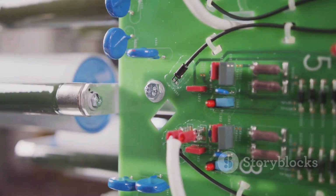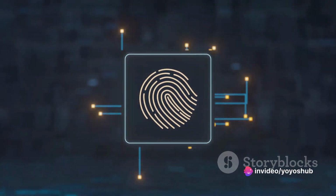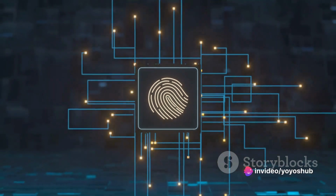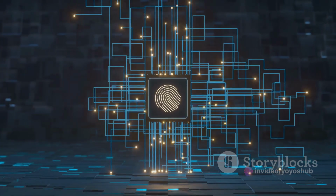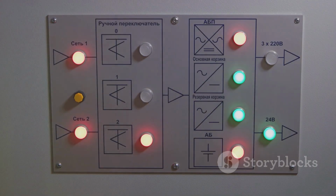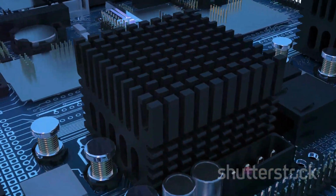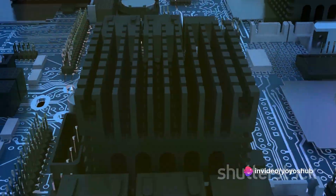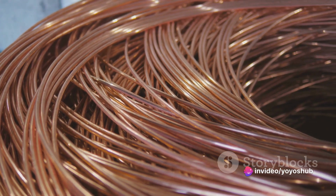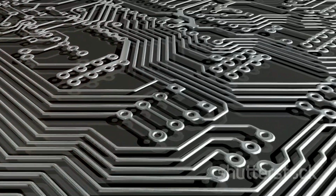Now representing these circuits visually is where schematics come in. A schematic diagram is a way to represent a circuit using symbols for each component and lines to show the connections between them. Think of it like a language where each symbol has a unique meaning. For example, a simple straight line often represents a wire, while a zigzag line stands for a resistor.